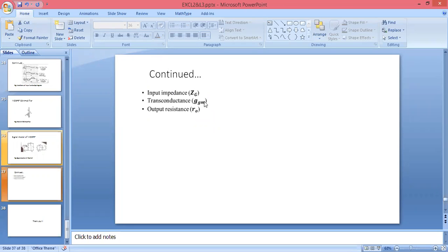मतलब ये जो रेशियो है वो क्या होगा? ऑपोजिट टू रेजिस्टेंस. रेजिस्टेंस मतलब क्या होता है? We can call V equal to IR. तो R को हम क्या बोलते हैं? V by R. तो ये ट्रांसकंडक्टेंस क्या हो जाएगा? I by V. So we are getting transconductance as gm equal to ID by VGS. And when we apply the output, when we are giving VDS greater than VDS saturation, what will happen? There is channel length modulation, and we will get an increase in current. That's why its output resistance will be 0, or negligible.